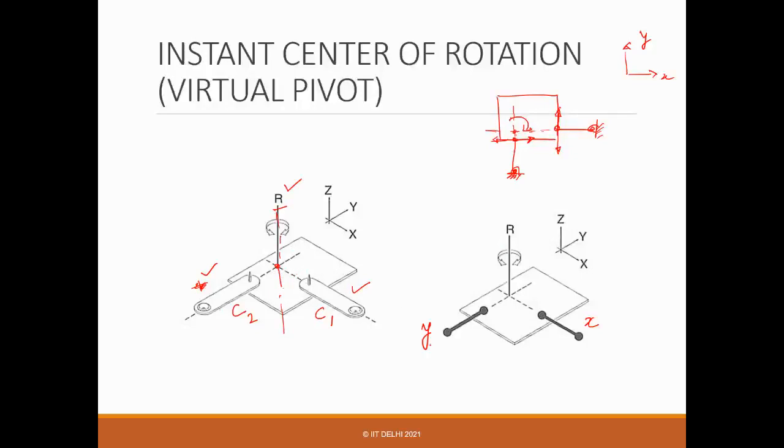So by carefully choosing these two, you can rotate an object without having a revolute joint there, right? We have the understanding that if you want a revolute joint on this object, you always have to extend this and then define a joint.